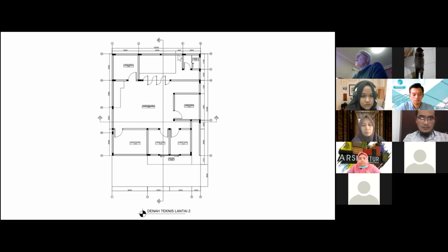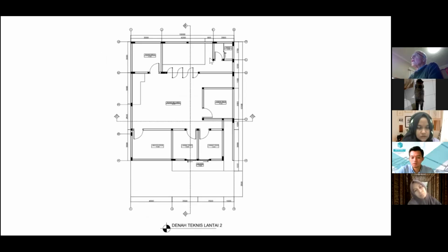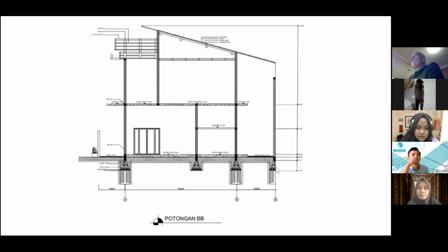And so the idea would be to have the rafters spanning this way, and then you put your battens for your tiles in this direction. And so the student hasn't designed a sensible structure for the roof. It's not sensible because these beams have to span 5 meters and they would have to be quite deep. For a timber beam to span 5 meters, it would have to be 30 to 40 centimeters deep. And the student has shown these beams being about 10 centimeters deep, maybe. I don't know.